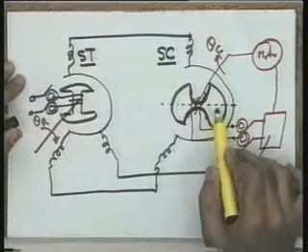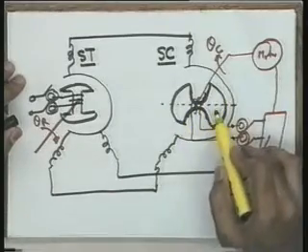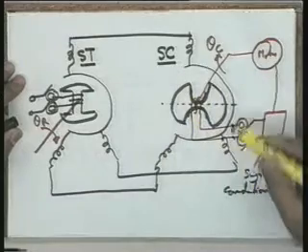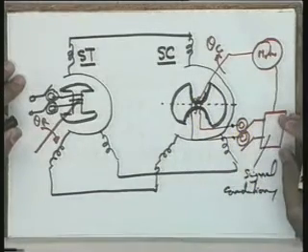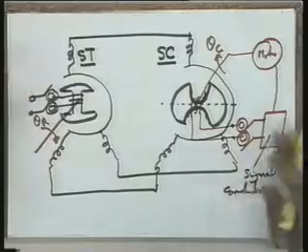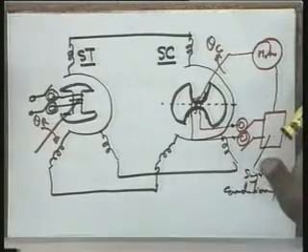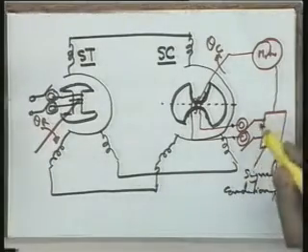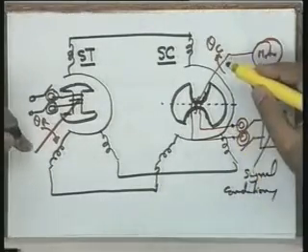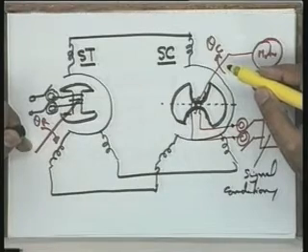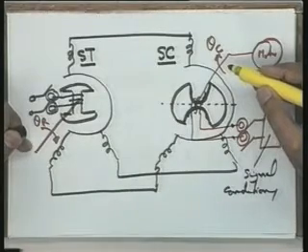there is a demand on this particular rotor to be cylindrical, so that the impedance seen by this signal conditioning device should not be a function of the rotor position. Now, the requirement of this is that a signal which is proportional to the difference of the two shaft positions should be available to us.